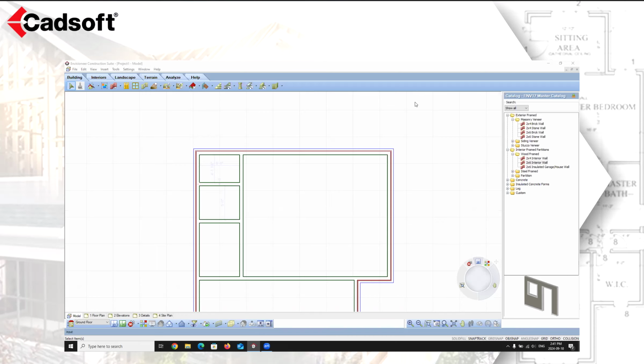If you are creating 2 different wall types, like for a stepped wall or stepped foundations, you have a foundation wall that's poured concrete, and then on top of that, you're going to have a framed wall. That would require a separate location, but I don't see why you would need 2 locations for the same type of wall with just differing heights. Those walls can be selected and edited differently. Let me know if that is the answer to your question there. I'm not sure I'm understanding that one exactly.